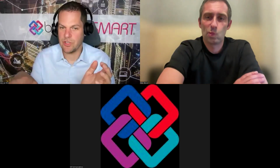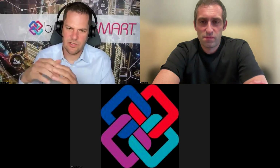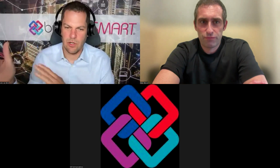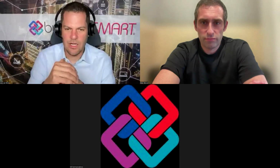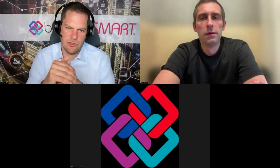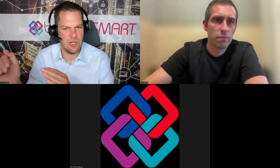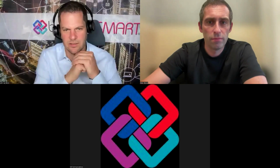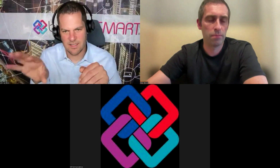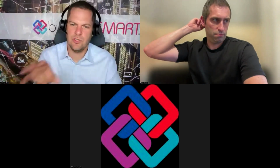There are software tools that do that. IDS is really intended to define the requirements of the information that you need to then perform these checks. So if you want to do a clash detection on geometry, you have an IDS that says all of the objects need to have geometry, and then you use a software tool to actually do the clash detection on that geometry. So IDS is intended to provide you with the information that you need to perform the design checks for your project.